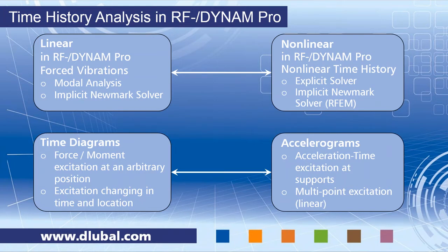You define loads and load cases to define the location of the excitation. So this makes it very flexible. So you can define nodal, member loads, surface loads, or even free or generated loads. So you can excite the structure everywhere, wherever you want. And time diagrams and load cases are then connected together in the dynamic load cases. And using this, you can even simulate an excitation that varies not only over time, it can also vary over position. The time history analysis of oscillograms, this is an excitation at supports.